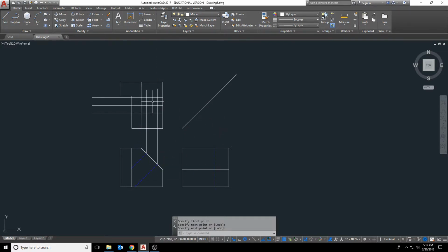and that gives me, right here, the rectangle that I'm looking for where that hole is going to pass through. So if I use these as my cutting edges, I can trim out everything that I'm not using right here. I know that I'm going to need to put a couple of these lines back in a minute, but it's a lot easier for me to do it this way rather than trying to figure out some other way where I have to create additional work for myself. So we'll go ahead and put in our ellipse right here, and then I can erase all of these.